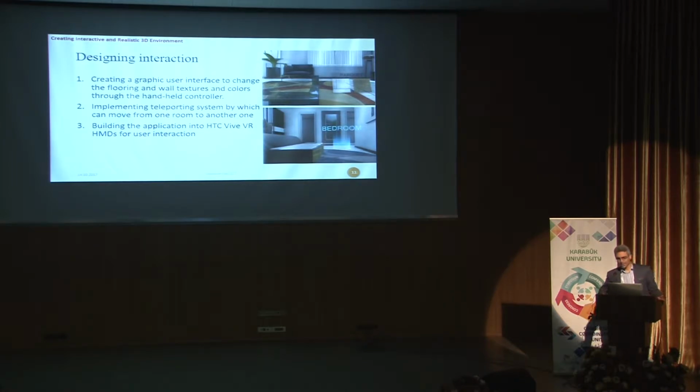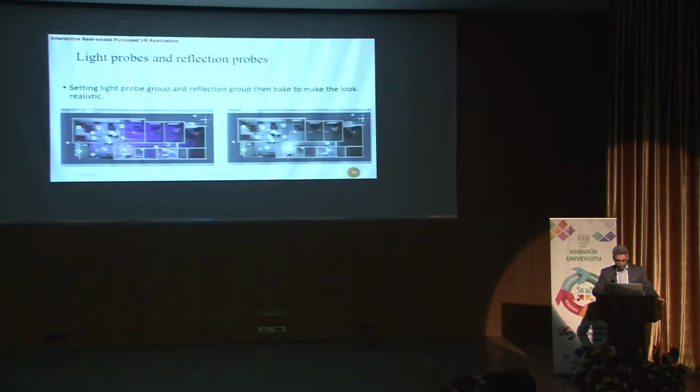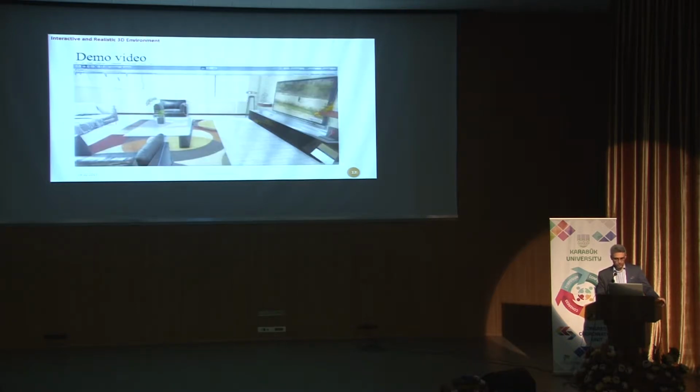So this is not enough for a good-looking 3D application. You need something more. You need light probes and reflection probes so that you can create them and the system can precompile them for you and calculate the reflection of, for example, a glassy material, and when you run your application it will be ready for your interaction. And the final step is baking them. It depends on your quality, but it will take less than an hour. It's ready to interact. So let me show you a video which